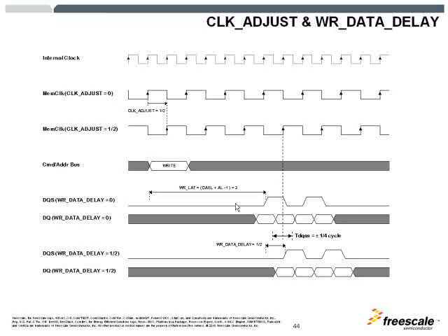So usually, if the clock adjust is set to 0, or is not set to any value other than 0, all the address commands and clocks are sent edge aligned, and I would expect that that system would fail quickly.